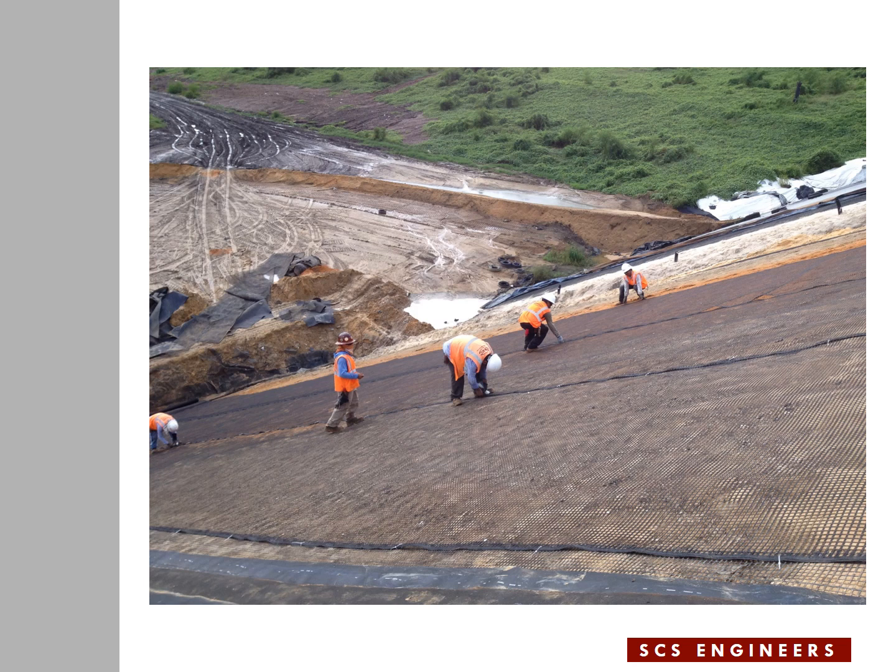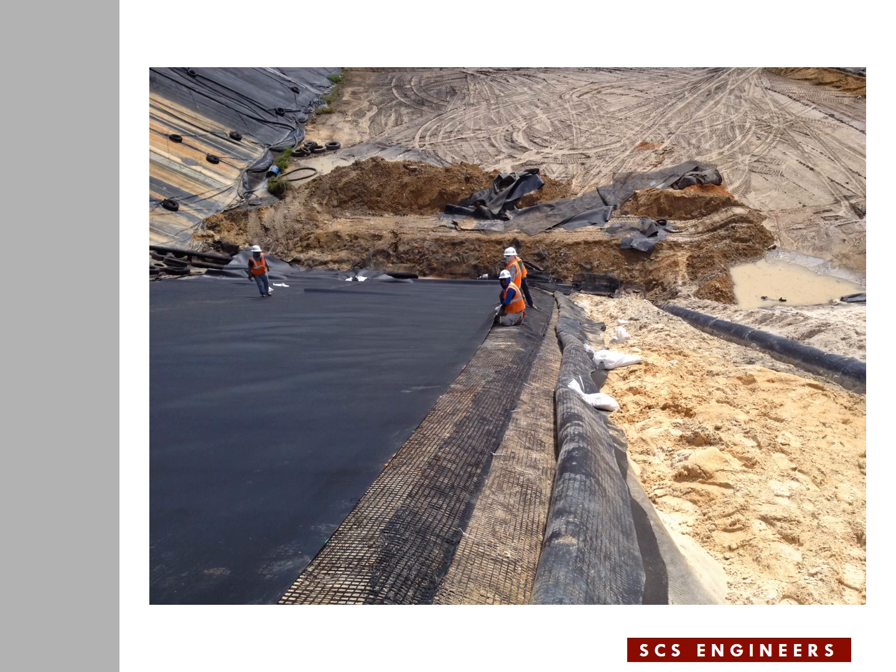Geogrid panels get installed and they get tied together using plastic ties. Then the geomembrane panels go in, and the geomembrane is a textured geomembrane, and the smooth edge of the geomembrane panel is visible here in the foreground. It's about 8 inches of smooth for welding two adjacent panels together, but the majority of the surface of the geomembrane is textured, and it goes directly above the lower geogrid.